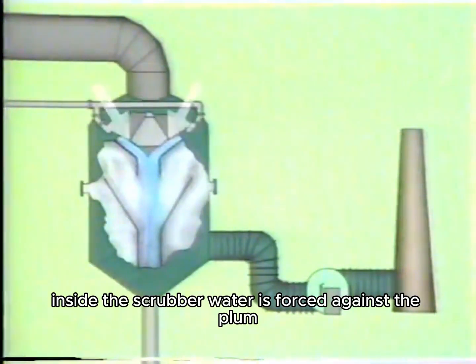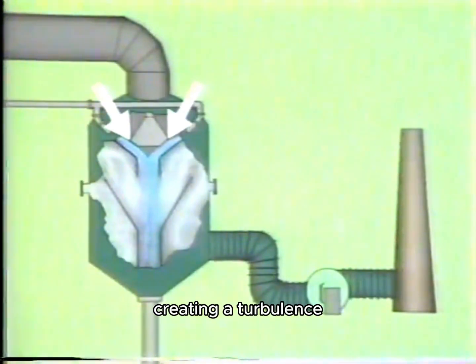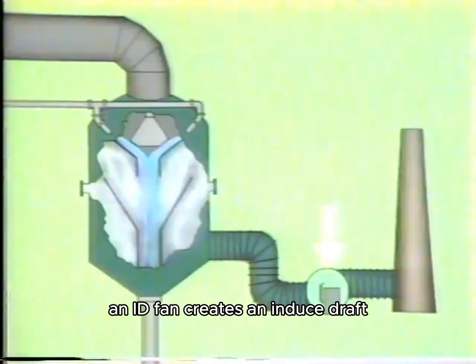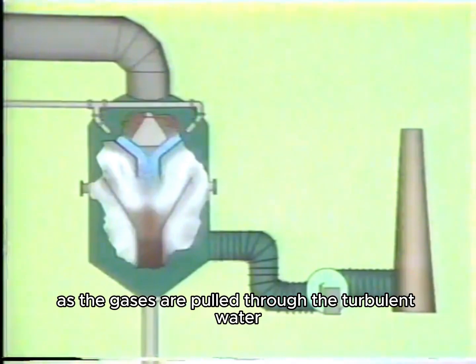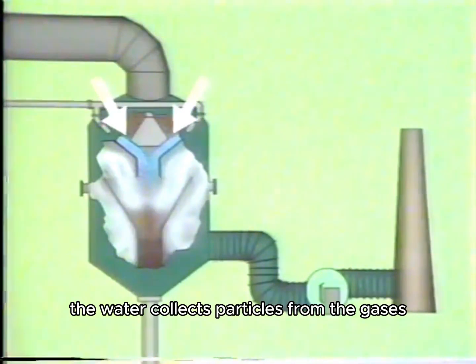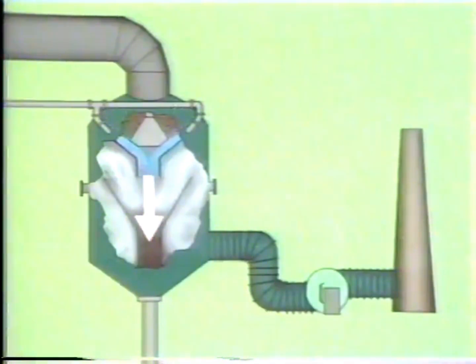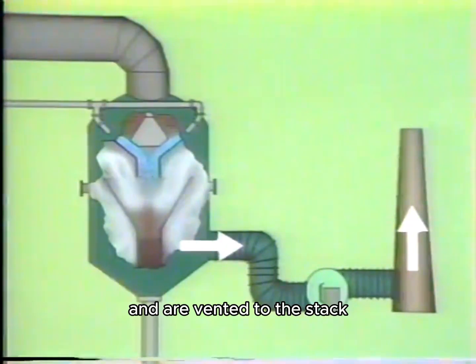Inside the scrubber, water is forced against a plumb bob and the walls of the scrubber, creating a turbulence. An ID fan creates an induced draft which pulls hot furnace gases into the scrubber. As the gases are pulled through the turbulent water, the water collects particles from the gases and falls to the bottom of the scrubber. The cleaned gases are pulled out through an exhaust duct and are vented to the stack.